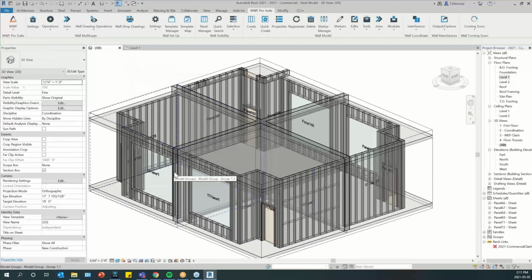The panels are not actually part of the group. The Revit group is one thing, and the panels, even though they are hosted in the group, are not part of the group itself. So you can just make changes in case you need. It will work exactly the same. You can add extra verticals, you can add joins, you can add markers to your windows. Everything will be pushed to the other groups when you run the command.